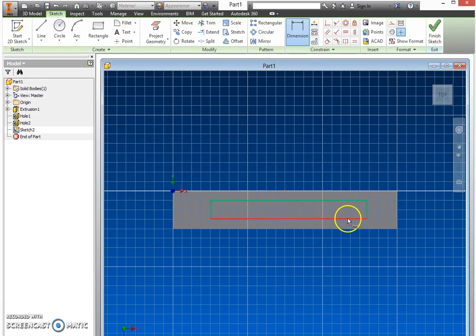First thing we're going to do is click the lower horizontal line of the sketch and the lower horizontal line of the rectangle. Okay, that's not the dimension we want. So if it doesn't appear correct, you just click, and then we can close that. To delete a dimension, you want to select the dimension and press delete, and it will go away.